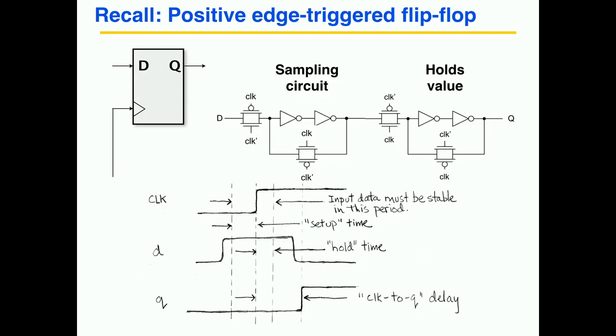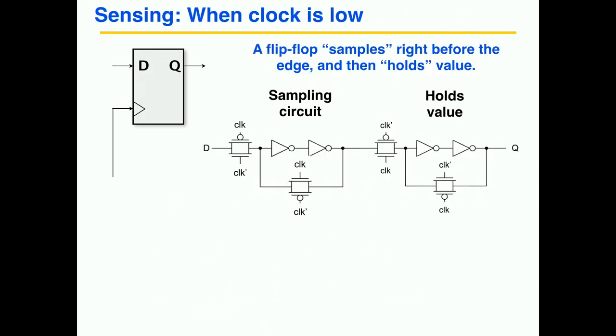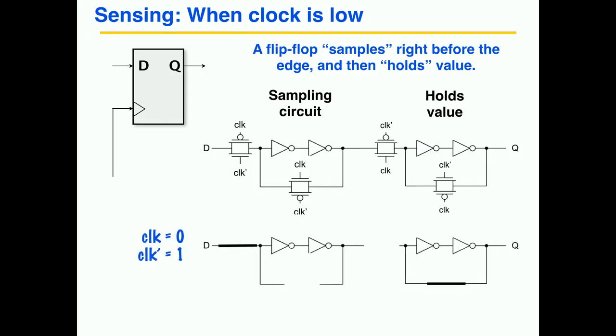So we're interested in asking the question, what's the origin of the setup time and the origin of the hold time? Well, if you recall, the way that these circuits work is that it works in two parts. When the clock is low, this latch is holding the value of the flip-flop and presenting it at the output, Q, because these are in a ring. This stage is transparent, meaning its input just comes out to the output and there's no feedback. Right?